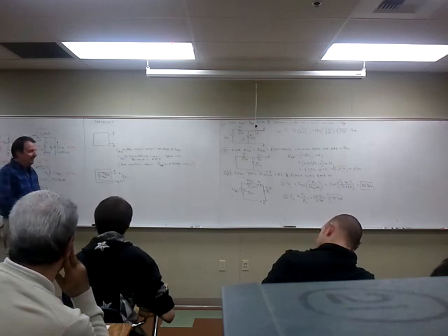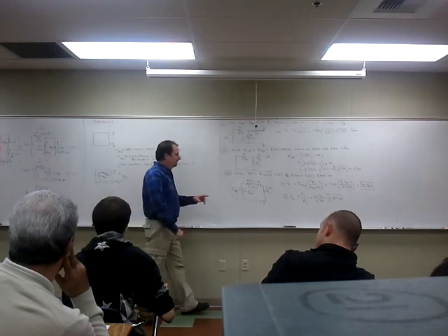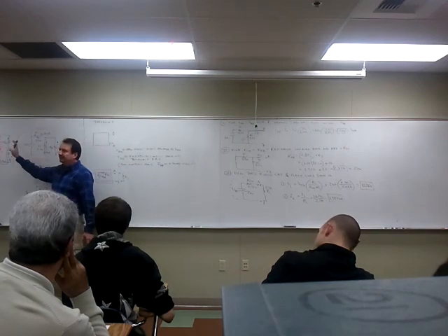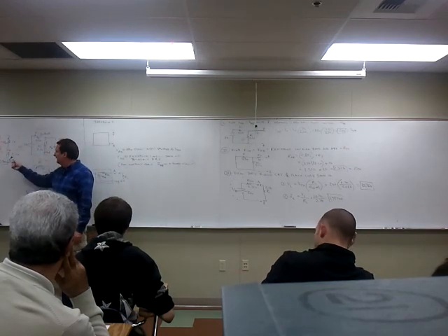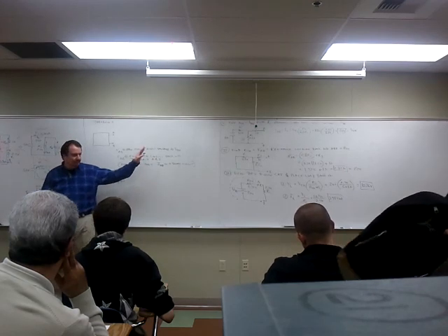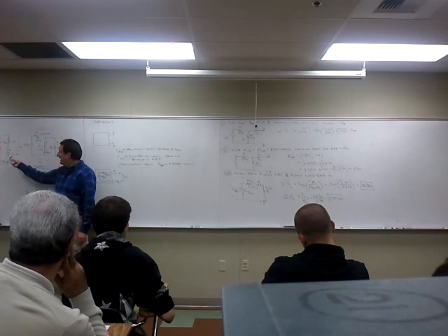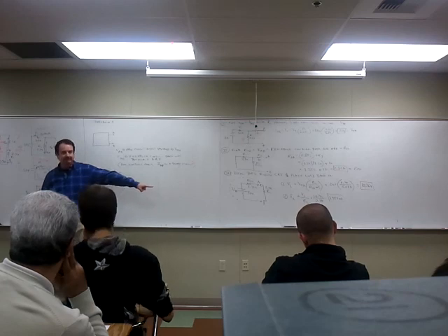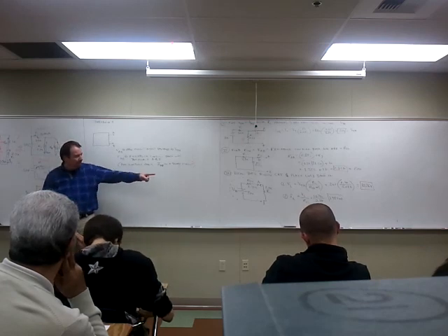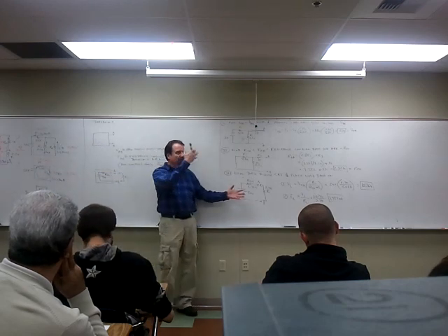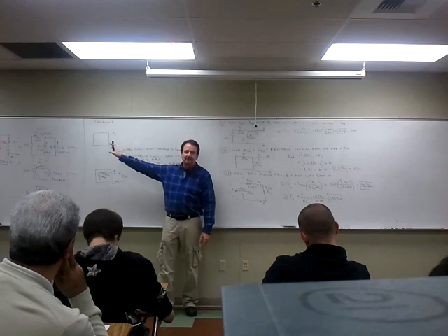Then again, why do we do Thevenins? Because what if we had to change many RLs? Let's assume it's a bigger circuit that took 30 steps to solve. How many steps would it take to get the Thevenin? Probably the same, close to 30 if you had to do a big Thevenin. But then after that, every time you change this resistor, how many steps is it? Only 2. That's a big deal. If you reduce a circuit to an equivalent, every time you change a load on it, it's this simple circuit that you have to think about. You don't have to think about all that trash.